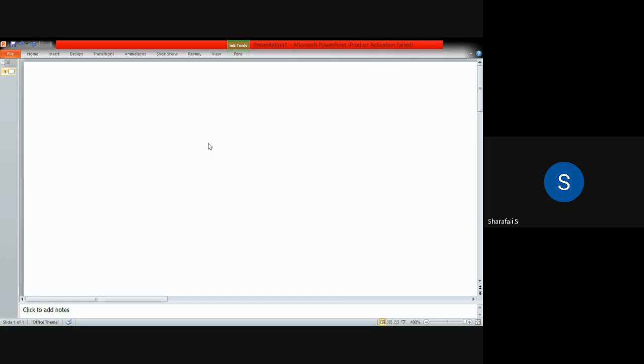So we have considered 2-bit case, and we connected an AND gate externally, and that particular circuit is called reset logic circuit. Because we have to get the value of clear equal to 1, that clear command has to be 1, so that the memory will be cleared.